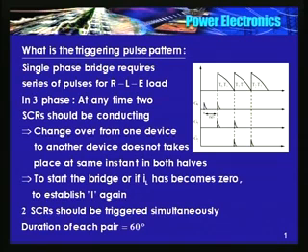By the way, this pulse should be shown. This is an ideal case. Please don't think that just because we are triggering again here, 6 will continue to conduct for another 120 degrees. No. See, you are triggering 2 after 60 degrees.